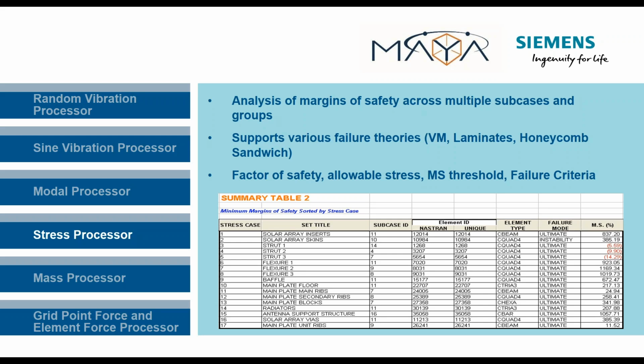So you're asking if you can... You have to repeat the question, please. So for beams recovering stresses, you're using the corner points, the stress recovery points, and I'm assuming that's initially what you're calculating the margin from. But a lot of times, you keep the forces, not look at the stress recovery points, and then you go in and calculate your margins based on the forces in that element.